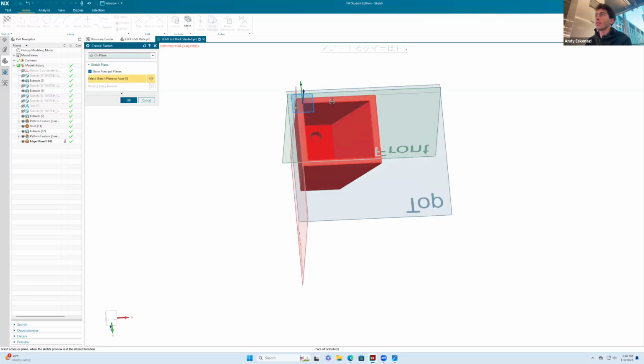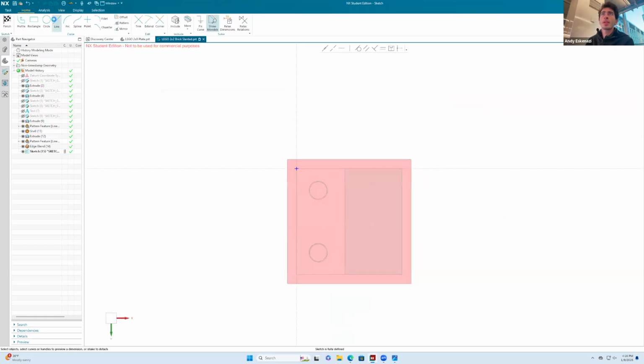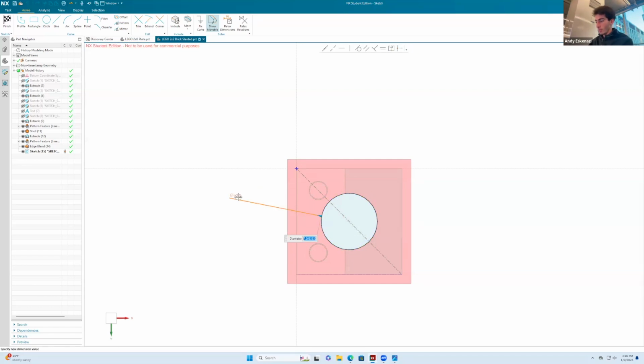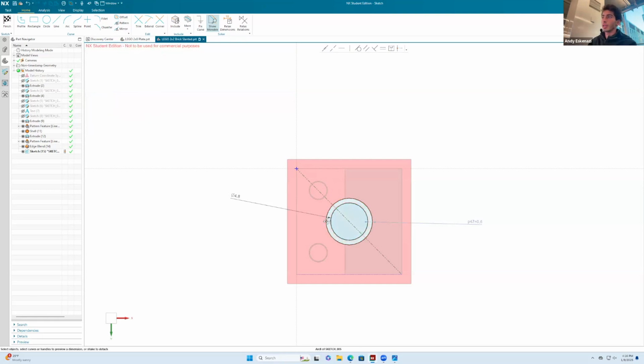In fact, I'm gonna go here, right to the middle of the sketch, and I'm gonna draw a line. Yes, that could go just like this. And we'll draw one circle of dimension 4.8, and this has to be offset by 0.6, exactly right.